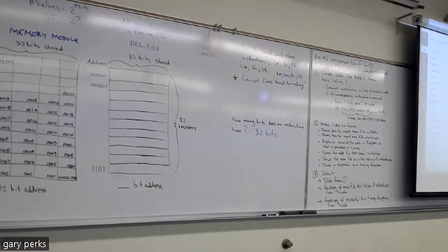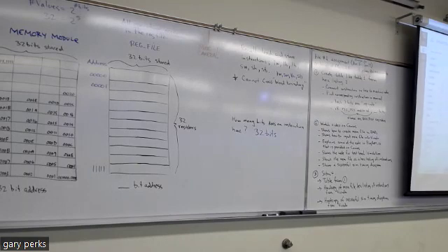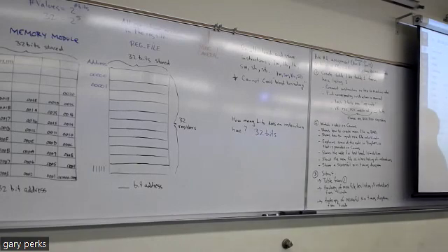Okay, and same thing over here for a source register, RS1. See, there's 5 bits. So those 5 bits are the address of the source register you're using. And now here, immediate is 12 bits. Well, that's the number. Question? What does RD stand for? Destination register.